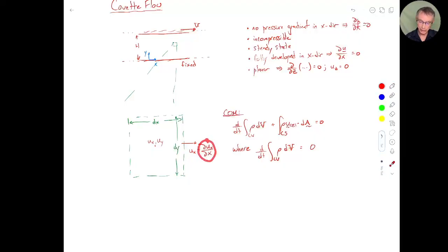So this is the change in the x velocity as I'm moving in the x direction, multiplied by how far I've moved to go from the center to the side here. And that distance is dx over 2, because I've moved from the center to that wall, so I've only moved 1/2 dx. So this is the velocity I start with in the center. This is how the velocity changes as I move in the x direction to get to that side wall. And then this is how far I've moved. So this is like my dux. It's just how much the x velocity has changed over that small distance.